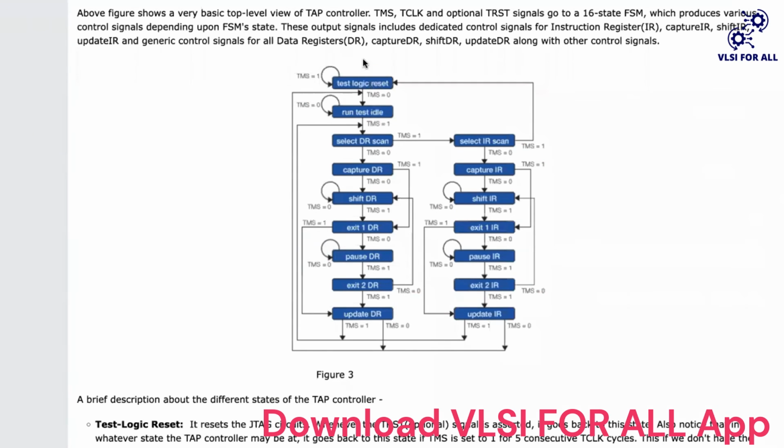That's why the industry standard has been made that TRST is optional. If a certain company wants to have a TRST, so that whenever I pulse the TRST it should come to test reset logic, then they should develop it. If a company is saying, okay, I don't want to add an extra GPIO for it, I will just do TMS equals 1 for 5 times and then it will get reset logic, that is also possible. And the use case of TMS is to shift between different states. So the different states which we were talking about are the different states which are needed for the JTAG.